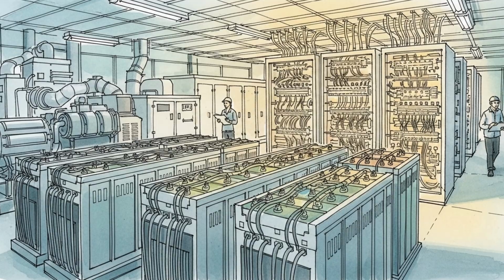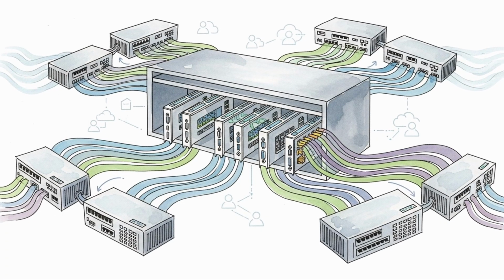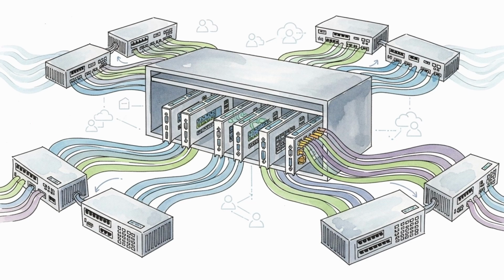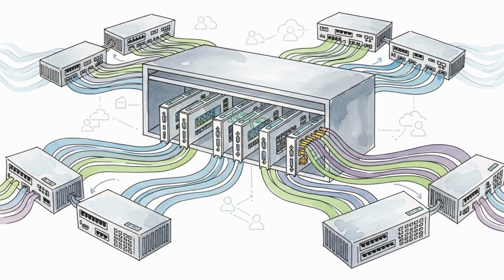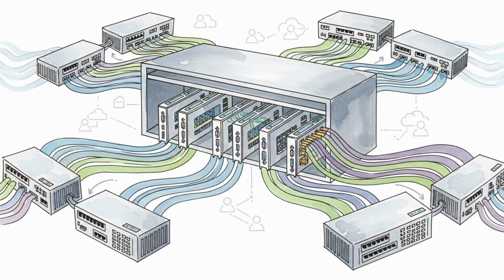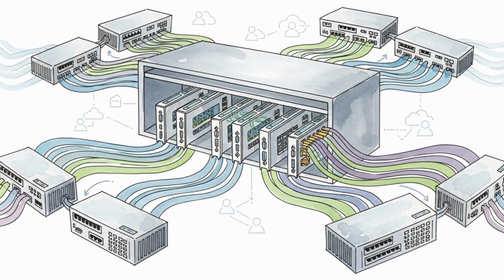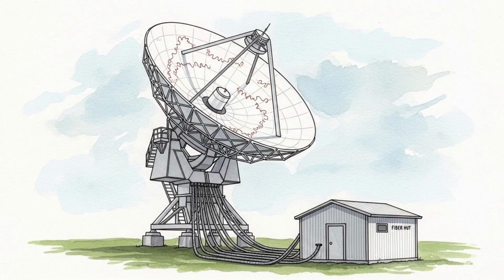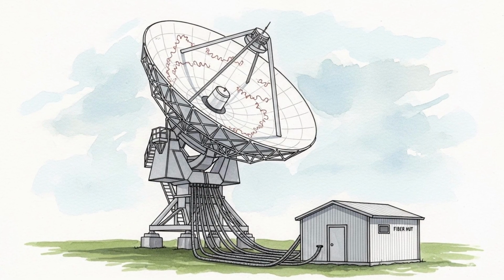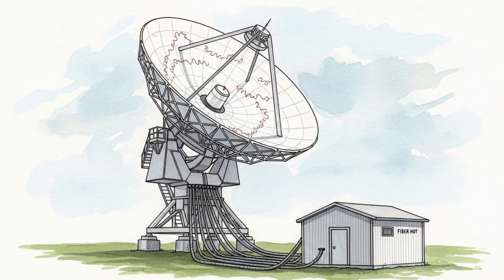Increase elevation masks to reduce low-angle paths that cross disturbed ionosphere at long slant ranges, accepting fewer satellites in view. For critical timing, combine satellite timing with local holdover oscillators and with terrestrial synchronization where available. Document performance targets for storm conditions so that automatic thresholds are known in advance.